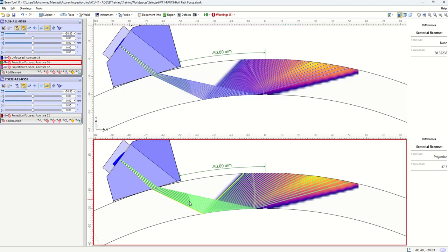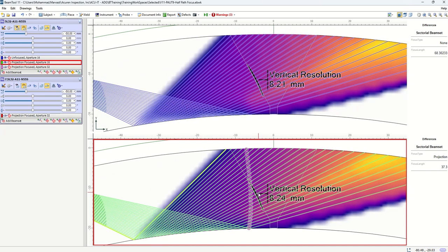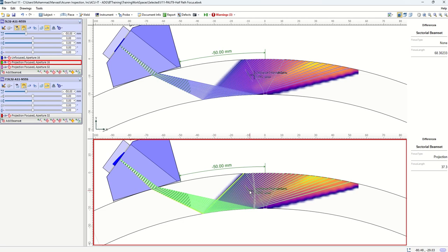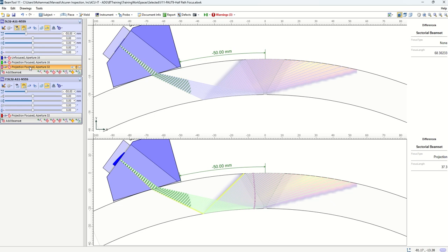So you can see that we are trying to focus at a location that is already far from our near field. So it's not surprising that our focusing does not improve anything, because we are effectively not focusing. So now, how can we improve this? We can improve this by changing the parameters in our technique that can increase the length of our near field, such that our near field gets extended to our imaging domain close to our bevel. And the main thing that comes to mind would be to increase our aperture size.